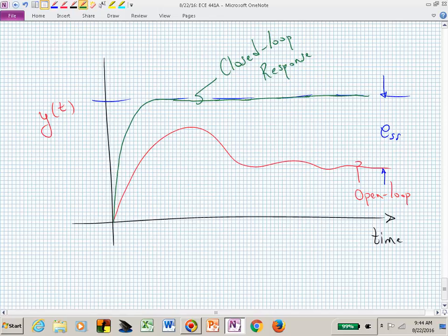And now what's the steady state error? Maybe it's 0. Maybe you've introduced an integrator. That's part of that PID. You now have an integrator term, and that's integrating out that error signal. It's trying to minimize that error to zero. You learned about integration in calculus. Now you get to use it as a tool.